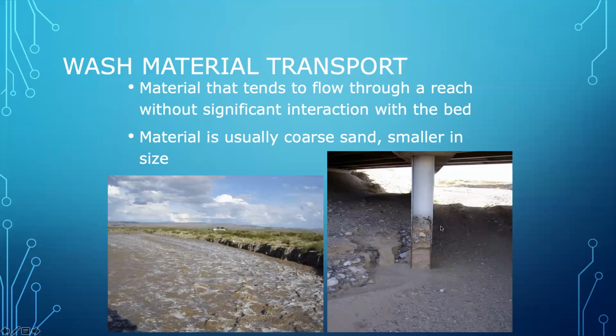Less so here. Now this is deceptive because you see the wheel tracks. There's been machinery moving up and down here. So this material was probably a little bit higher than it is in the photograph. But knowing the shape of this particular stream at this location, it's not surprising that there's deposition here on the inside of this turn, because this is the outside of the turn where the cursor's moving right now, and that's being eroded away by this water that's being redirected to come under the bridge.